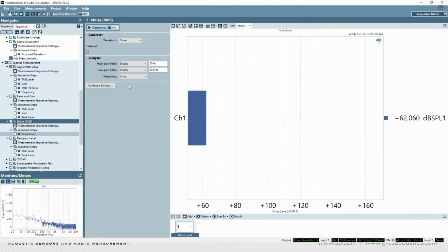That is a deep question. I will make the following statement, which we can follow up on, but it's really almost its own topic. An audio device that is linear and time invariant, so what I mean by that is an audio device where the output of a system has a linear relationship to the input of a system and whose behavior doesn't vary over time, will have exactly the same measurements regardless of the stimulus signal that's used. It could be multi-tone, it could be sine wave, it could be speech or music.